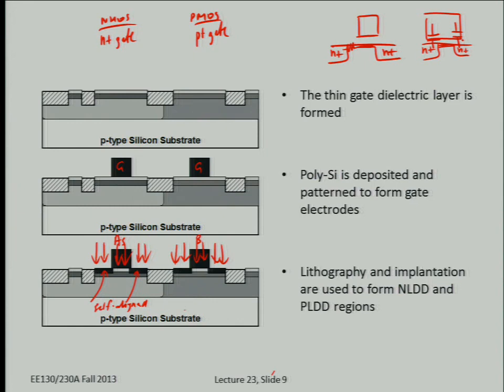Now you need to anneal. So this involves thermal annealing to activate. So we call it activate. We need to heal the crystalline damage and to get the implanted dopant atoms to reside on substitutional lattice sites, right? So they bond with 4 nearest neighbor silicon atoms. And that requires high temperature processing, usually greater than 600 degrees C, typically more than 1100 degrees C, depends. The peak temperature can be higher than that. So you need high temperature to heal the damage and to activate the dopants to get the conductivity to be high in the source drain regions.